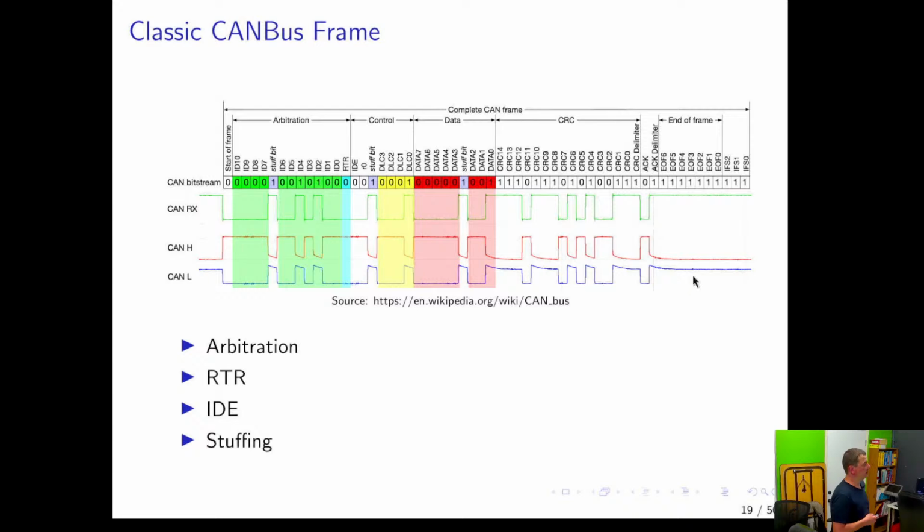One thing is the bus is idle when both lines, right? We have CAN high line, CAN low line here, and then this is the receiver pin on our processor, basically. And time goes this way. This is from Wikipedia. Also, this figure has been offset. In reality, if you're looking at this on the oscilloscope, these would be on top of each other. And CAN high actually needs to be less than or equal to low for it to be in this idle state. Makes sense?